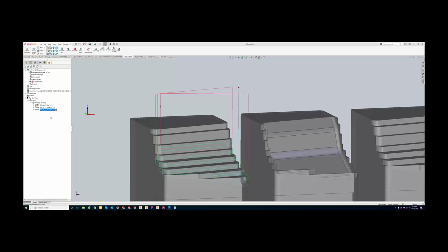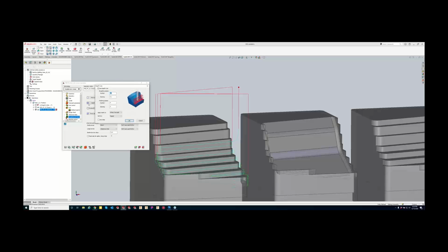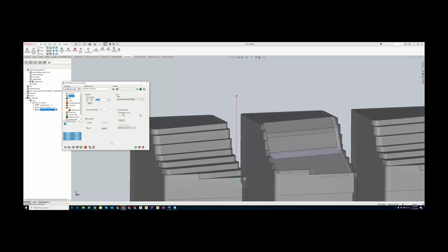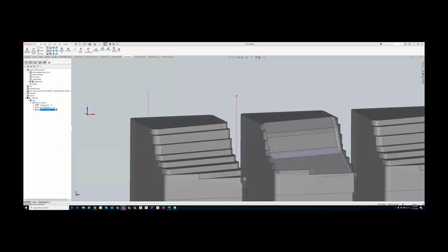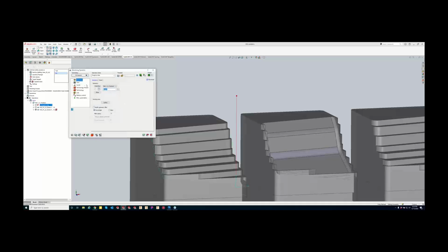Before we leave this part, can you turn off the roughing and more and the limit by points? Basically, I want to see the tool path along that entire surface using linear, and then compare it side by side with the tool path with constant Z. Because this sample part especially does a good job of showing what the differences are between the two, even though they're very similar tool paths. And let me go back to the iMachining here and put it back to where we had it. Oops, turn that off. I think I had this.